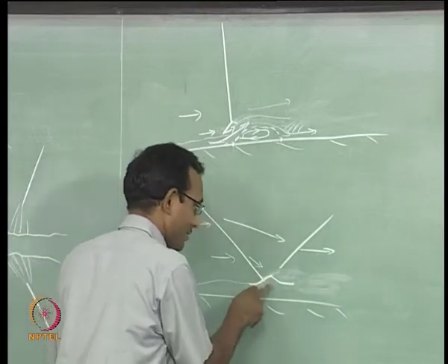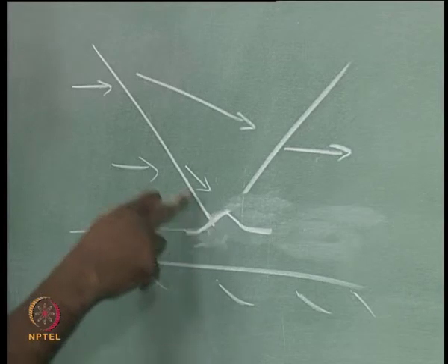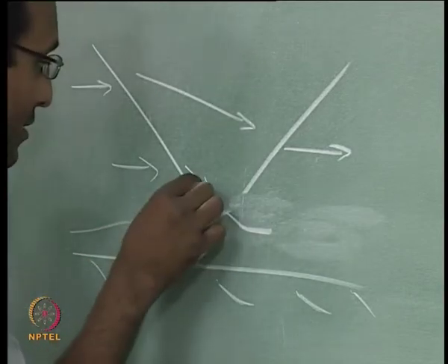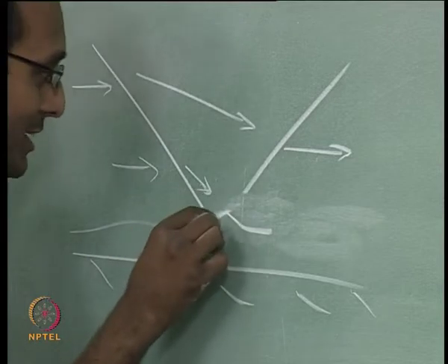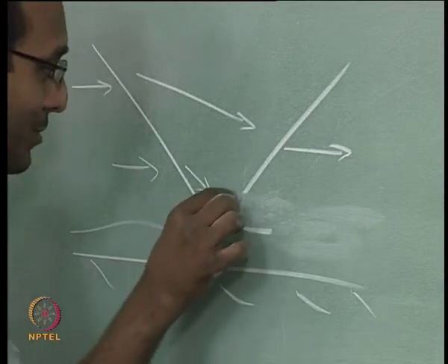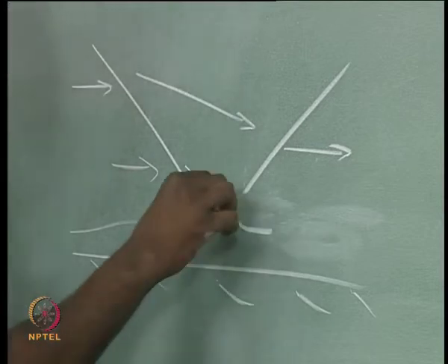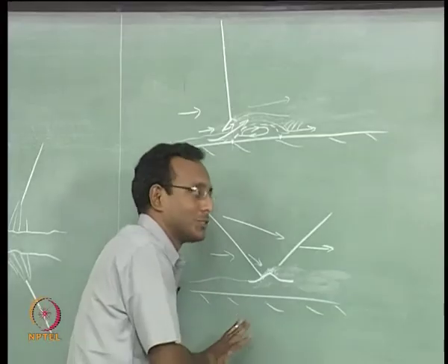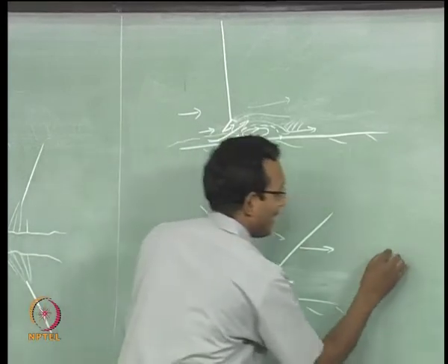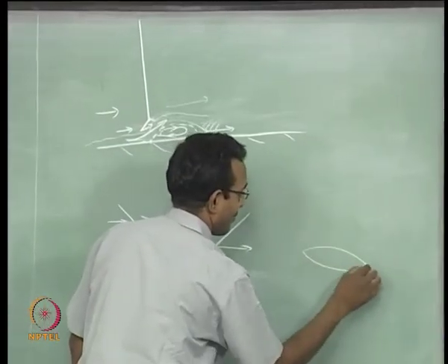Now when it is near the wall, when it is viscous flow, and there is some boundary layer tripping happening, then you will see that the flow comes like this, and then suddenly it is going to see a bump like this. So there is going to be a set of compression waves, they are all going to mix together, and there will be expansion waves after some time, okay, because it is a smooth curve similar to the airfoil we had before. Okay, it is at an angle of attack, let us say.